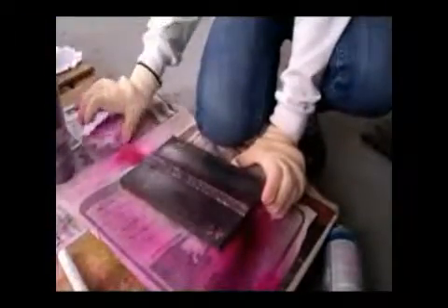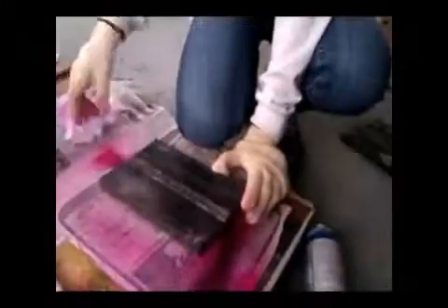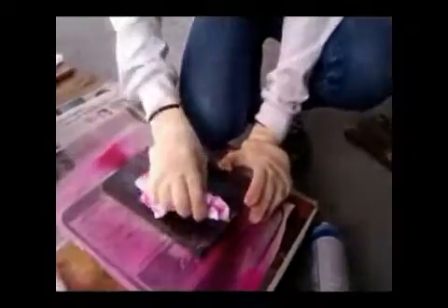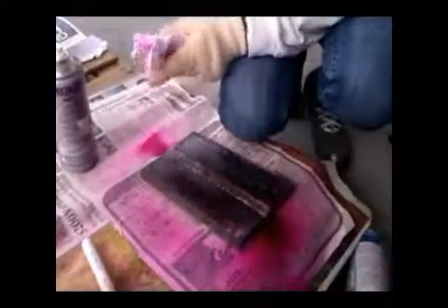Emulsifiers represent the highest sensitivity level, and chemically interact with the oily penetrant to make it removable with a water spray. When using solvent remover and a lint-free cloth, it is important to not spray the solvent on the test surface directly, because this can remove the penetrant from the flaws.